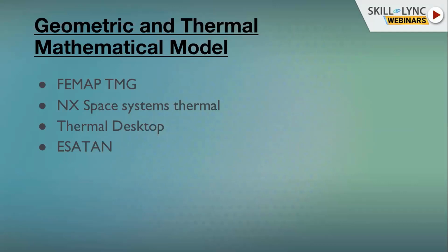For example, you need to connect one surface to another with a heat transfer coefficient. So based on the empirical relations and the area of contact from your CAD, you are able to determine what kind of contact conductance will be there between these two surfaces. Like this, you make a network for all of these components, whether they are bolted, glued, or welded. You do a contact conductance calculation and you enter it in the model.